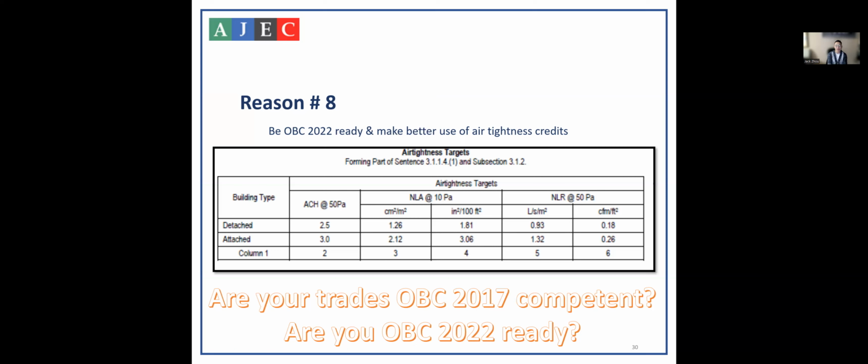I do a lot of air tightness training, and this is something you have to do if you want to comply with net zero, or if you want to comply with the next version of building code. Without doing air tightness, you have to spend a lot more money to make it compliant, because you have to get more insulation, better windows, better mechanical system just to comply. And air tightness doesn't cost money. It's all about details. If you execute the details properly, you will hit these targets.